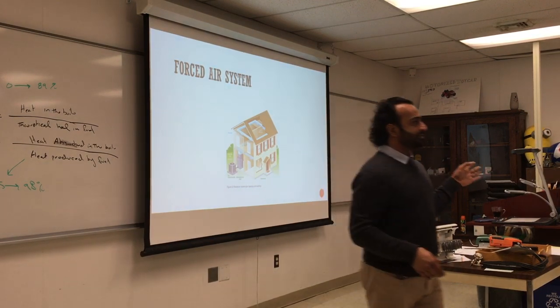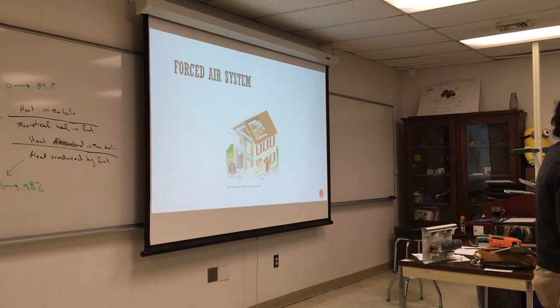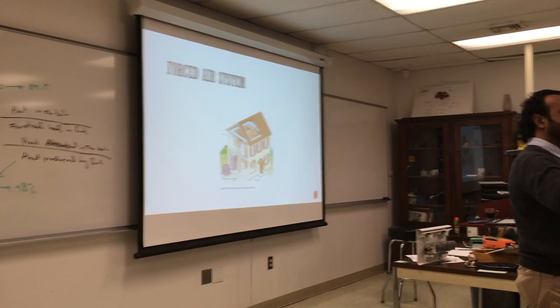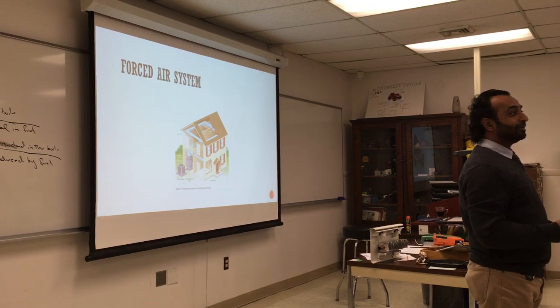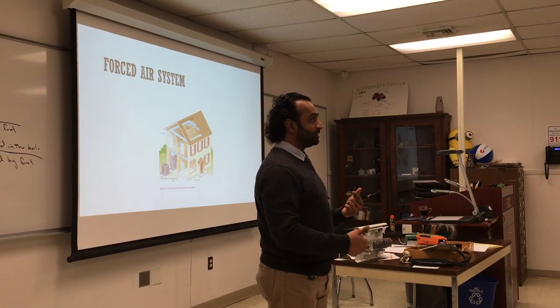So when I have a duct system, ideally you want the duct to be some in the bottom and some in the top, to have the least amount of forced air coming into the room. So in the wintertime, you want the hot air to come from the bottom, to rise naturally. And in the summertime, you want the cold air to come from the top. So some central airs do that. They will switch and reverse the intake and outtake.